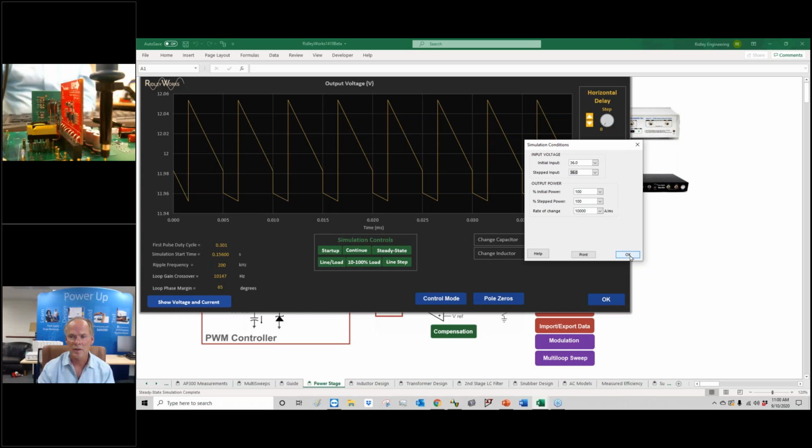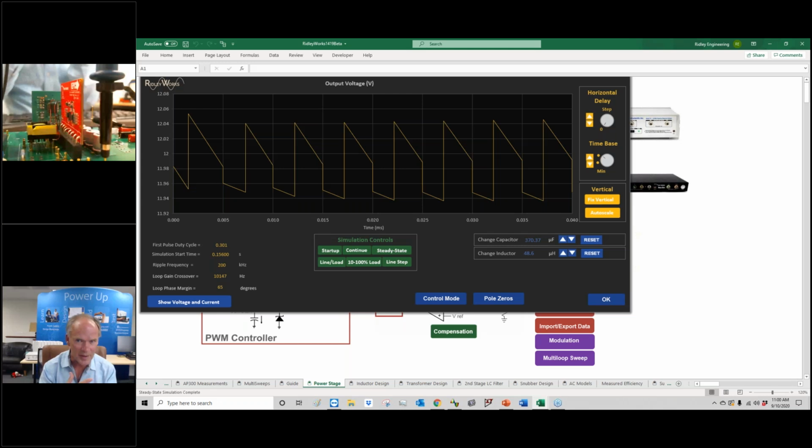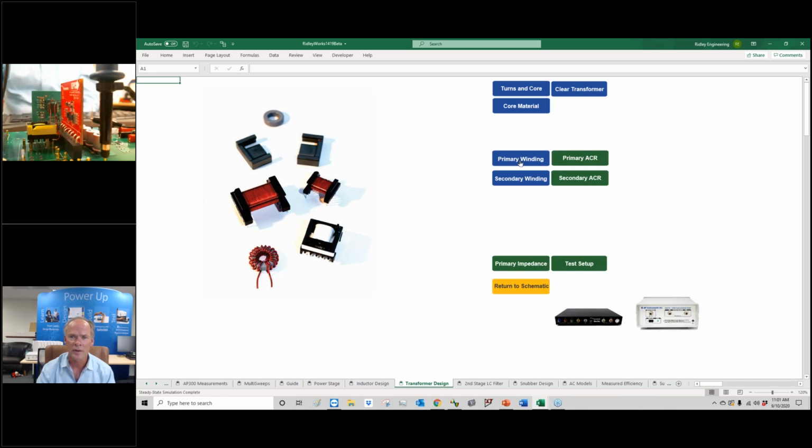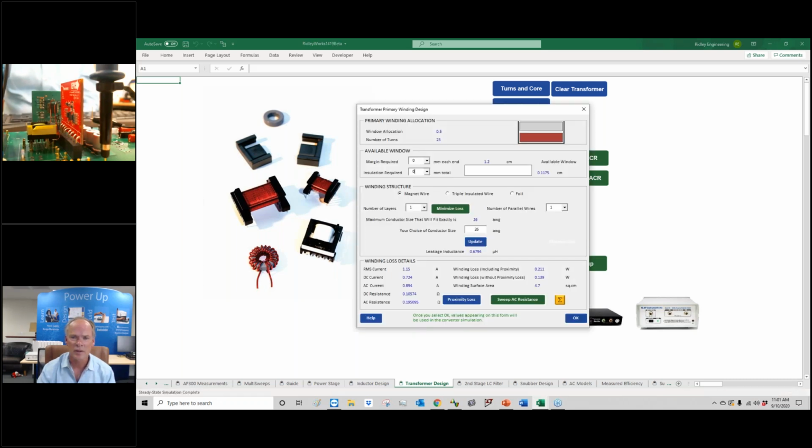it'll change. So we have this built-in simulator. These are not just calculated losses, we simulate, because you can't have closed form equations for anything in a converter, not even duty cycle. There's so many things that get involved in duty cycle. We run a simulator, then we analyze the waveforms. And that's what we use in our design pages here. Okay, so now you see that's up to the 0.2 watts that we had before on the primary.